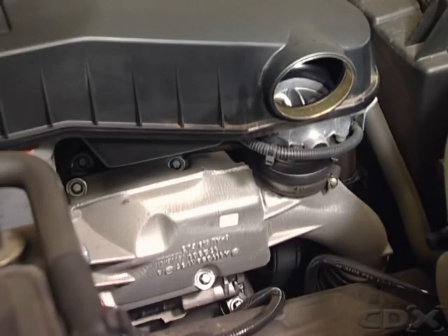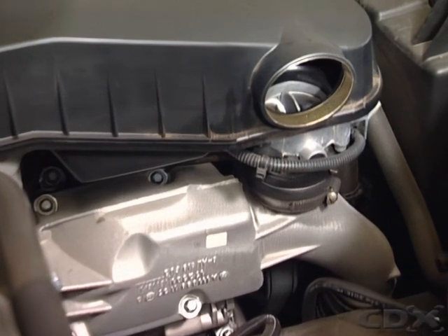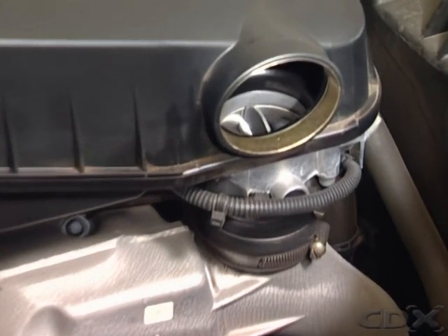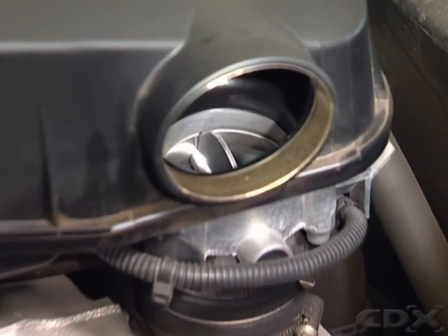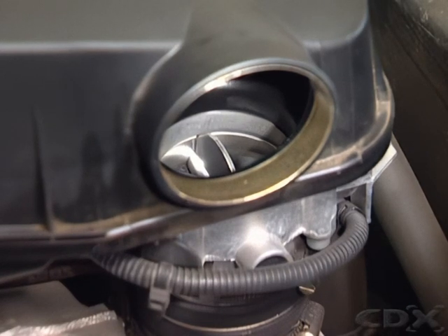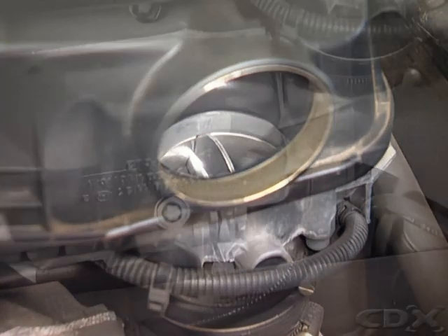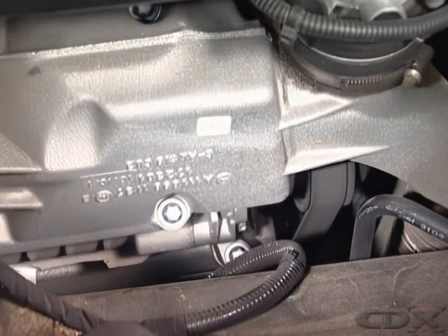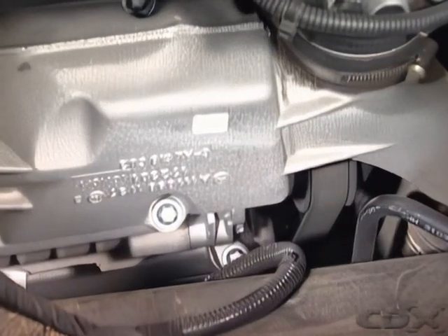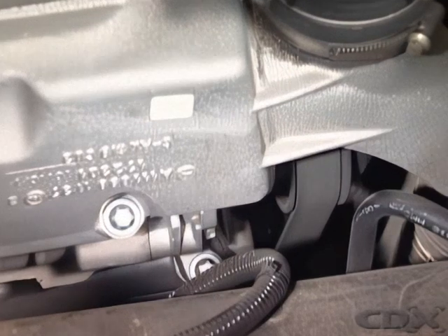Both engines use a large throttle opening but induce a small amount of air. This results in lower manifold vacuum, reduced pumping losses, and increased efficiency. The Miller cycle engine adds an engine-driven compressor to the intake system to boost power output when required.